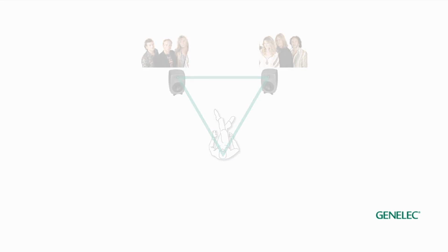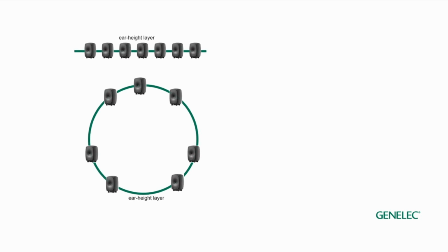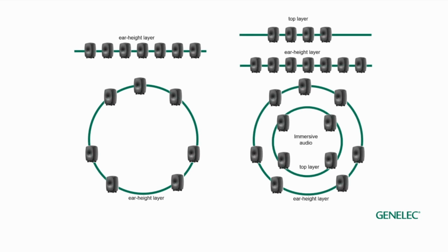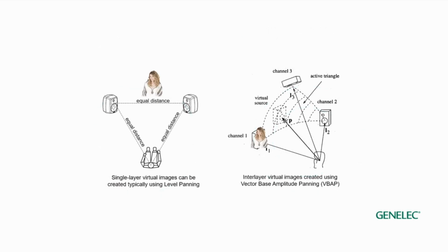Today, we have much more complex sound reproduction systems. These new reproduction systems surround or immerse the listener, and they can present complete sound spaces. We need a lot of loudspeakers for these. But the same principles also apply for surround and immersive layouts. It's important to follow what has been agreed for directions of monitors and aligning the system for level and delay at the listening location.